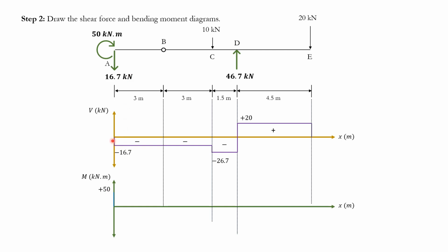And now I go to my shear force diagram. The area under the shear force diagram is what I'm looking for. You can measure it from here to here or from here to here. At the hinge, I must have a zero moment. And automatically I will, right? It doesn't really matter which way you go.